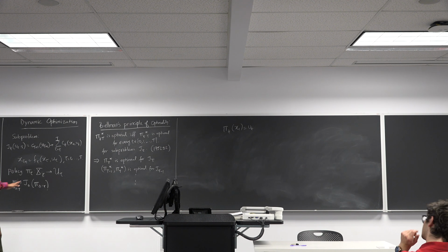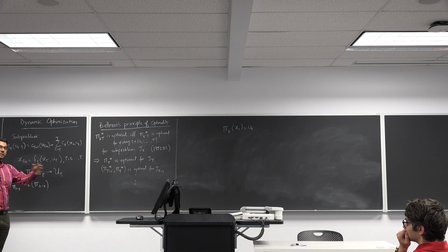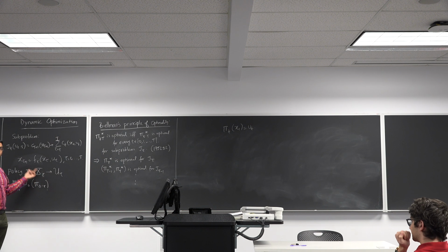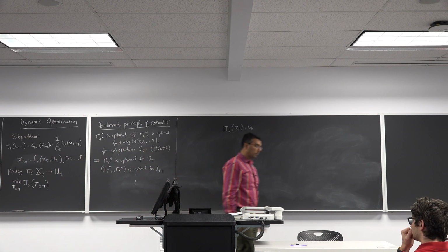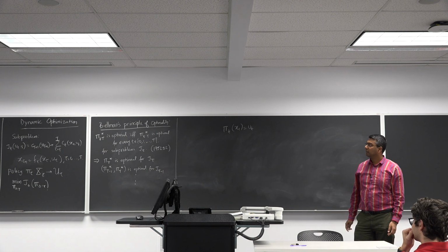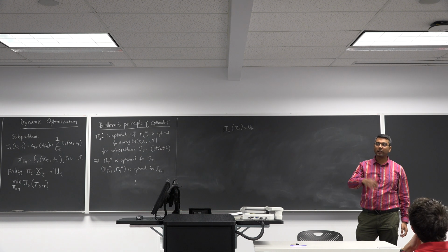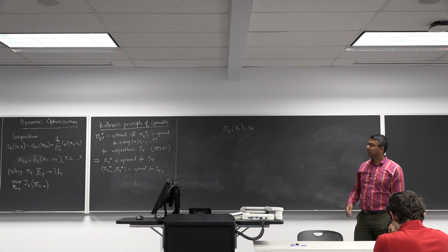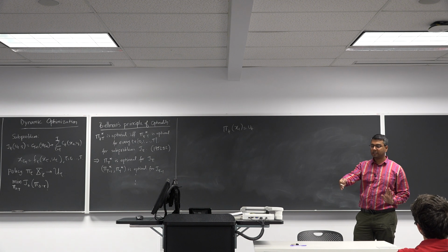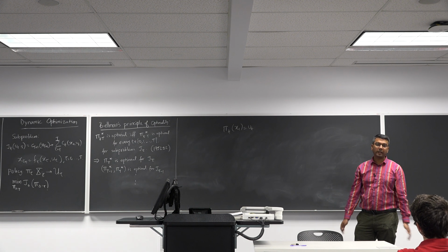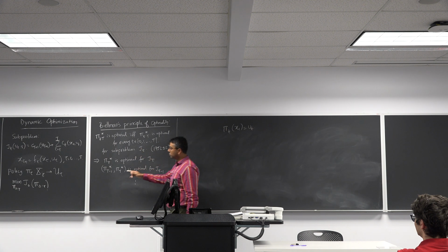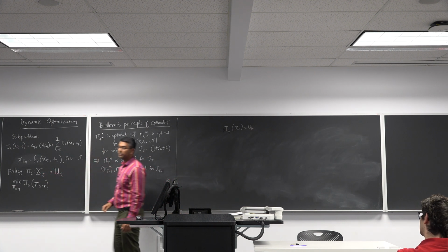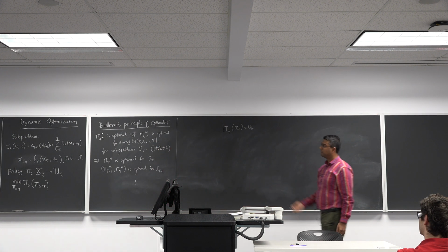So if the wind blew and instead of xt star you are now at xt star plus epsilon, this policy will tell you what you need to do at that particular point, because it's a function of state to action. So it will tell you at every state what you should be doing. Okay, so if you think about it from, let's say, the chess perspective, when you're playing chess, it's one thing to say, move your horse, move your elephant, pawns here and there. It's another thing to say, if this is what the chessboard looks like, if this is where the adversary's pawns are, then this is the best move for you. So that's the difference between an open loop policy, which is ut star, versus a closed loop policy, which is a function of the state. You are observing what's happening, and on that basis you are taking an action.